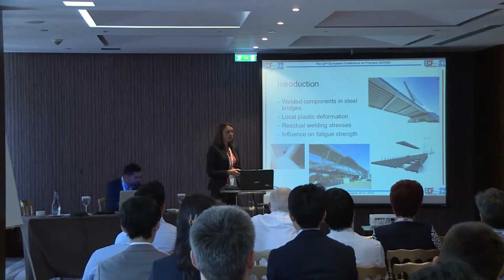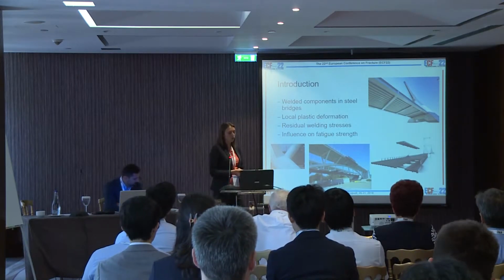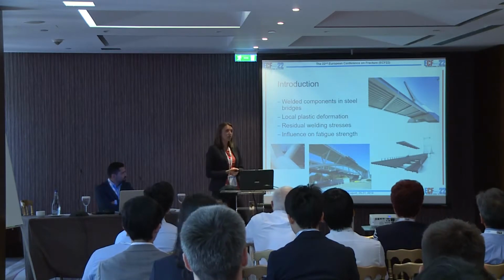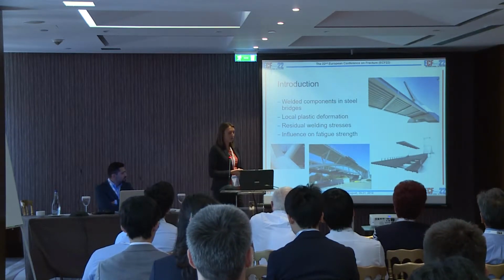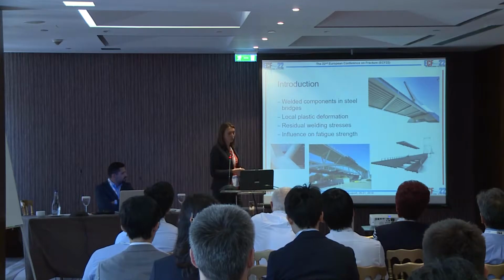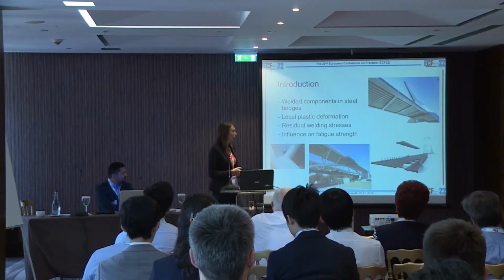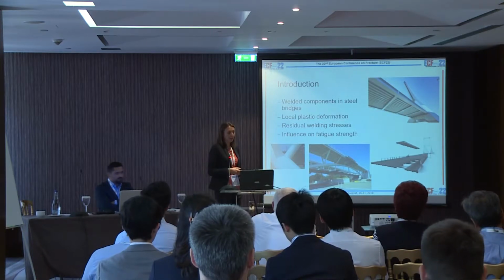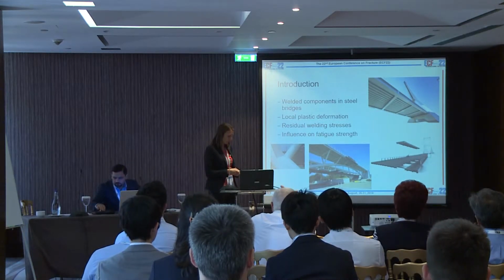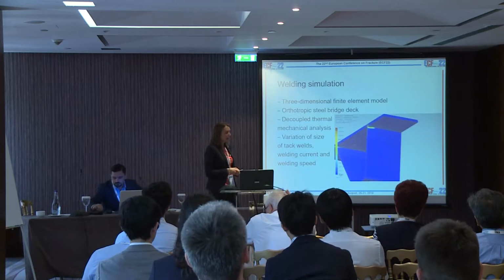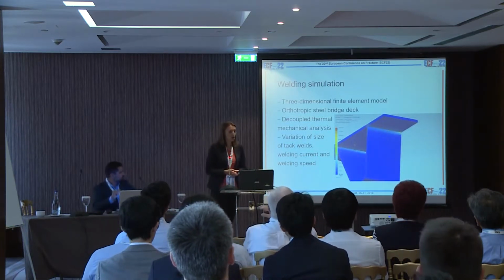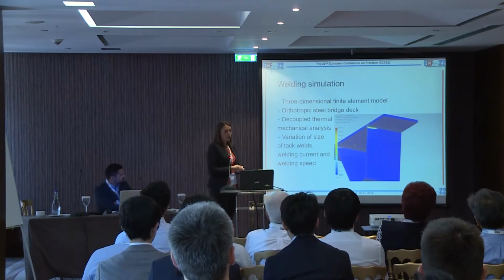Residual welding stresses are introduced due to the welding and due to local plastic deformation. These welding stresses can have a large impact on the fatigue strength. We have to avoid tensile residual stresses being present, since they tend to open cracks and they increase the crack propagation rate.